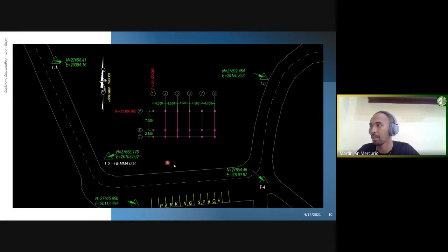structure or markings, diba? As you can see, it is a distance away from the construction site. If you put these controls near the site, diba, the tendency is they get disturbed, they get lost, and so on. Also, they may get damaged or get in the way. So it's very important: not too far away and not too near.